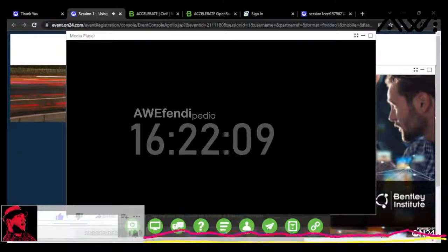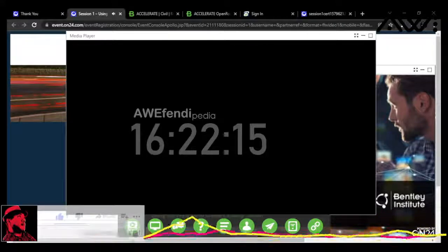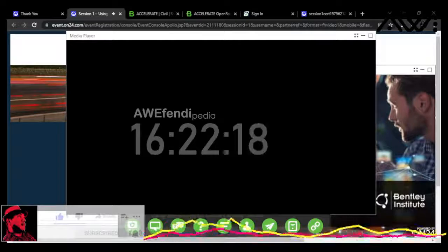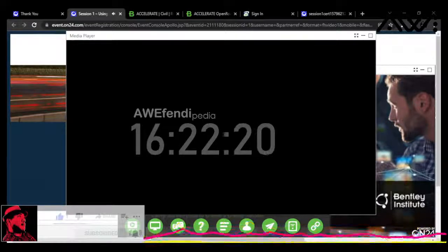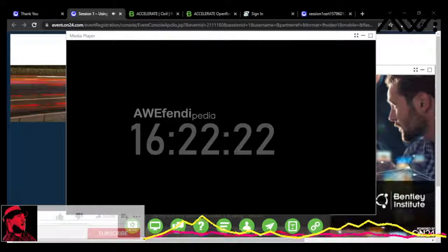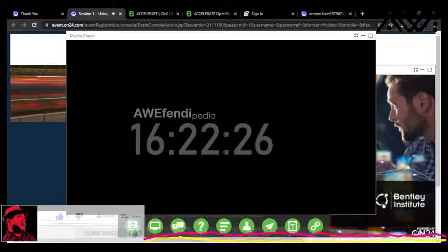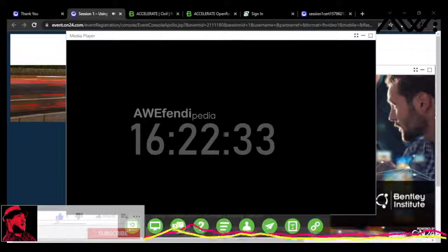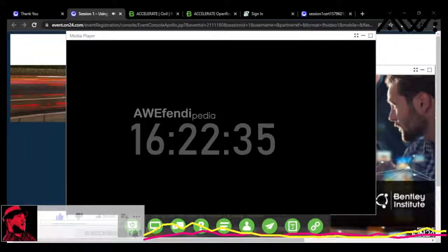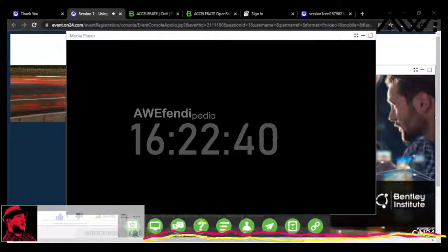And to do that, we're going to go up here to our bridge deck, which is running over our stream. And you can see we have a problem here. We have, again, probably a different string number from the east side of this bridge connecting up to the west side abutment. So we have a bust there. And now I'm going to start talking about using a point list feature, because I don't want to really have to worry about the order in which these points exist in the field book, right?